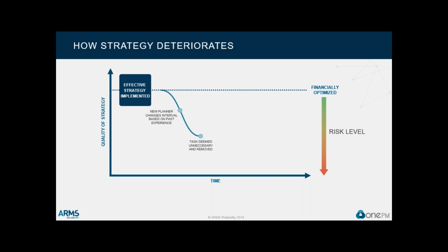because we need to be thinking about things like the PF interval, things like what's our warning time from when it starts to deteriorate to when it fails. We need to be thinking about what's the failure behavior of that asset. We can't just say that because we haven't had an incident, had an event, or seen any deterioration, that we can remove the task. We just can't do that. But we often do. We see it happen in many different facilities that we work in.